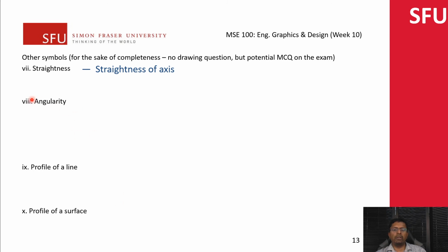The next one we're going to look at is known as the angularity constraint. This is a generalization of the perpendicularity constraint. Imagine you have a line or a plane that looks like this. We have a reference here, and then you have a plane. The angle would be, say in this case, about 60 degrees. That would already be given to you. That will be the theoretical value, so there is no variation applied on it. Then you have a tolerance zone, and the value over here.